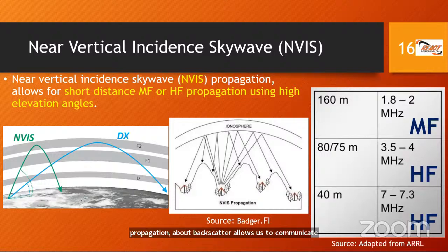Right, so yet another technique, we learned about this the last time. It's called NVIS. What is NVIS? We said it's near vertical incidence sky wave. That's another way we can drop our signal short in an area that we would not normally be able to. In other words, the ground wave wouldn't reach and the sky wave wouldn't reach, so we could try using NVIS, right? So we're trying to shoot the signal almost straight up, so that it bounces or reflects or refracts and drops short, as opposed to a low angle of radiation where it will actually go all the way across the other part of the earth.